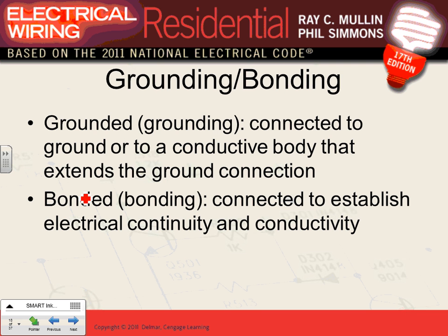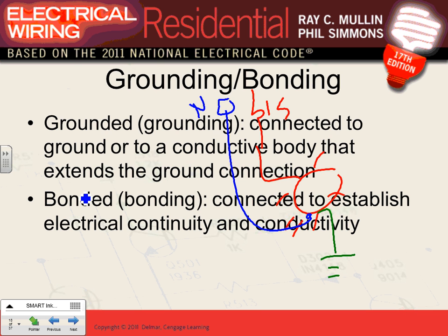Now, for the electricity to work efficiently, you need the second wire. So you grab the hot from a 15 amp breaker, you land it onto one side of the light. From the other side, you drag it and bring it to Mother Earth. That will work. Now, that's for the system to work. To work efficiently, we bring back the return, we bring it back to the panel and put it at a neutral.